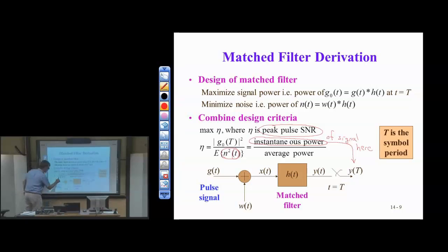So this is really the expected value with respect to little t of the noise process squared. In other words, it's the expected value of the instantaneous power of the noise. And again, expectation simply means average whatever is inside over the duration of observation. Now, in homework problem set number 4, you dealt with expectation quite a bit over finite observation.